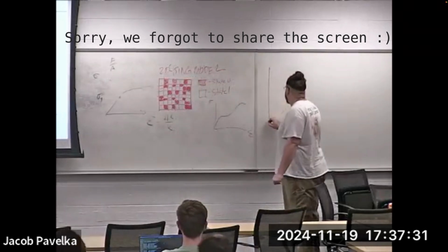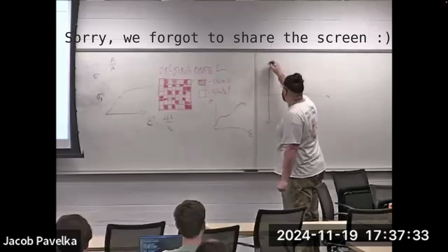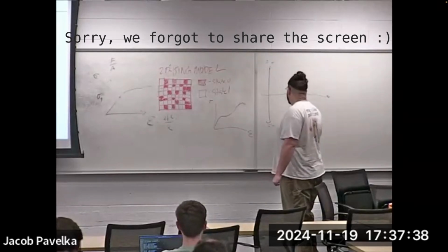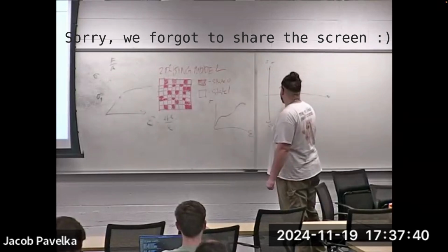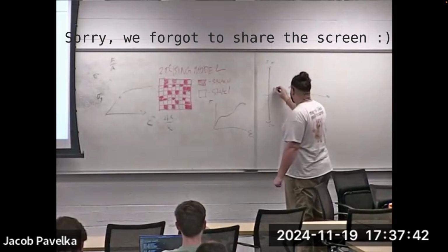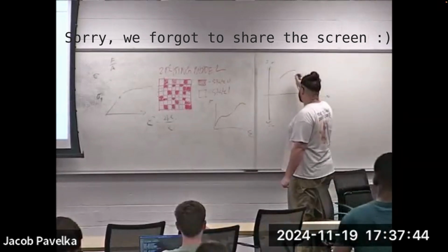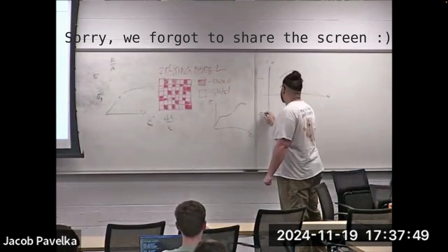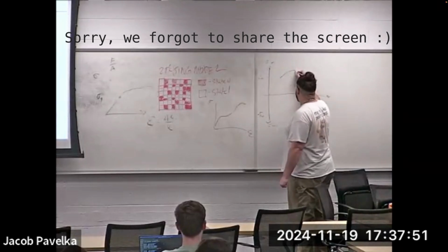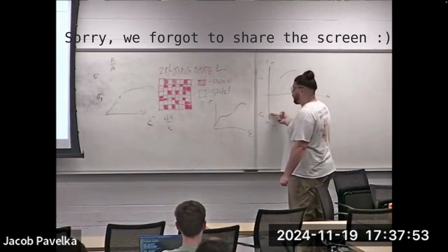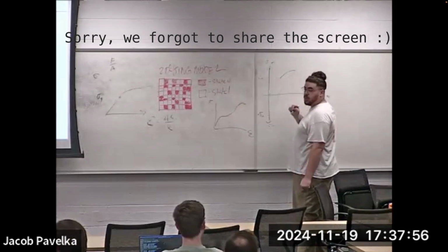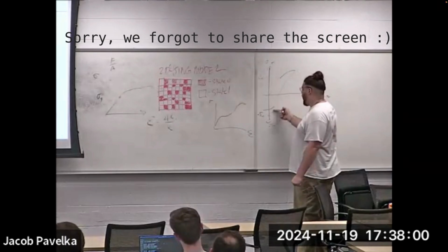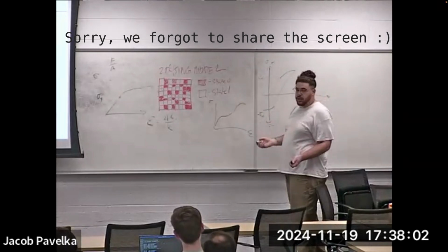Kinematic hardening is like, say this is the positive and this is negative. So if I loaded it and then it had some plasticity, here is sigma y and here is minus sigma y. When I come down, before it reaches the negative of this sigma y, it is going to start going plastic. And how much that happens, that's called kinematic hardening.